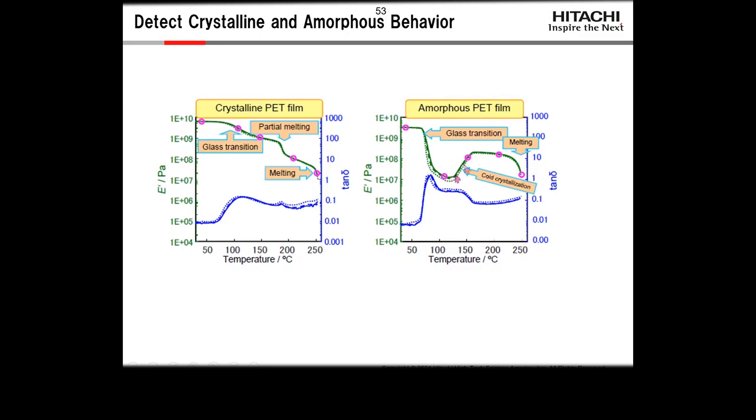In PET and in silicone rubbers, after you go through the glass transition, the material can rearrange and you can get an actual increase in modulus where the material forms more crystals in the run. And while you can pick this up in the DSC, you can only pick up the temperature change. You can't see what kind of change this makes in your modulus behavior. In PET, it doesn't make that big a difference, but some of the silicone rubbers are actually stronger after the cold crystallization than they were before.